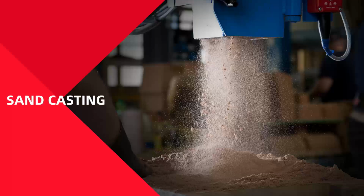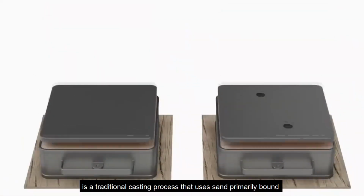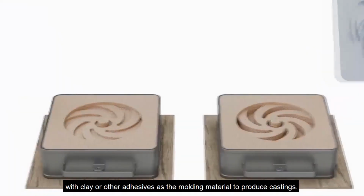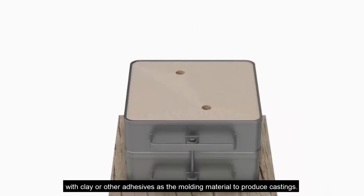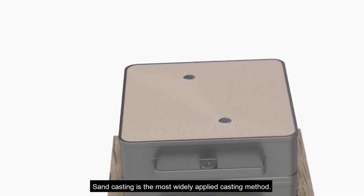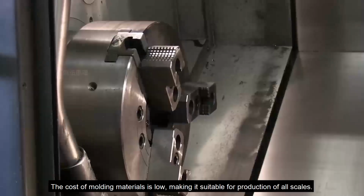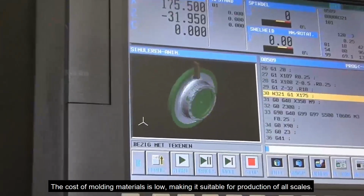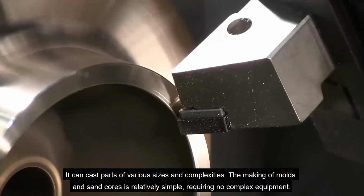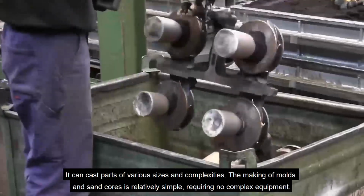Sand casting. Sand casting, also known as sand mold casting, is a traditional casting process that uses sand primarily bound with clay or other adhesives as the molding material to produce castings. Sand casting has the following characteristics. Sand casting is the most widely applied casting method. The cost of molding materials is low, making it suitable for production of all scales. It can cast parts of various sizes and complexities. The making of molds and sand cores is relatively simple, requiring no complex equipment.